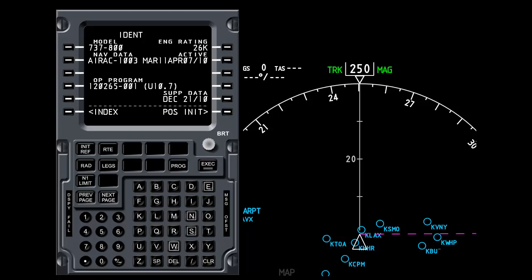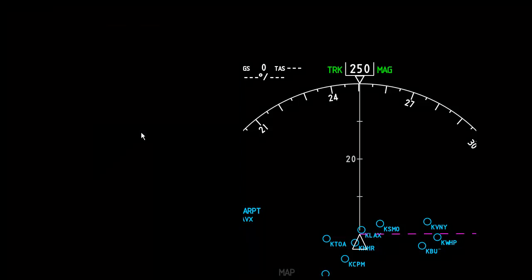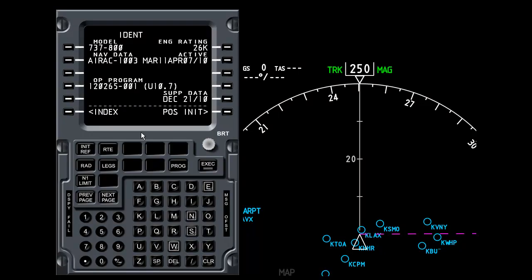Part 2 of flight planning, we're actually going to program the flight from Los Angeles to San Francisco. Now you'll notice here on the left we have a screen that may or may not be familiar to you. This is called the control display unit, and this interfaces with the flight management computer. So if I press the F2 key, that will hide or display the CDU.